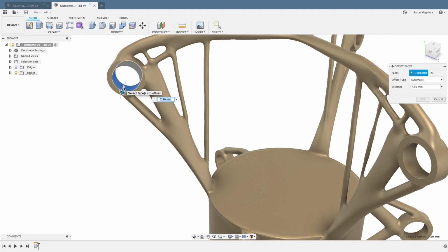When I do this, I've often been perplexed where these initial values came from. Most people can figure out that that's the existing dimension, but if I type in 3mm here to offset by that amount, I'm going to have a bad time. Turns out there's an easy way to alter this input to do what I want. Just hop over to the type and change it from automatic to new offset. This will allow me to drive this in the way I intended.